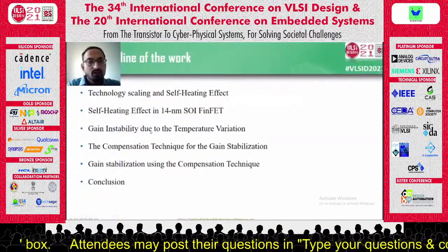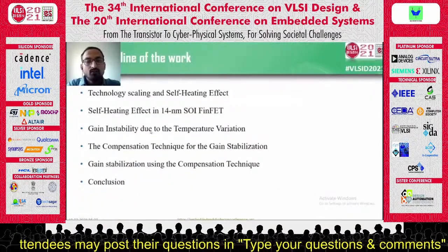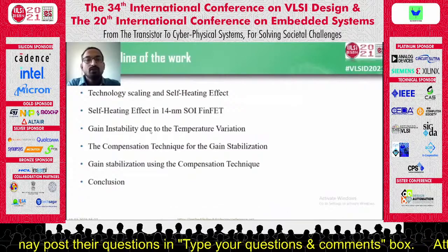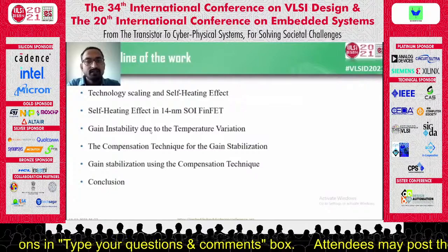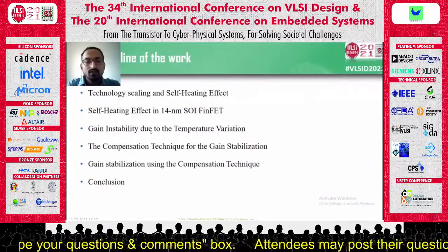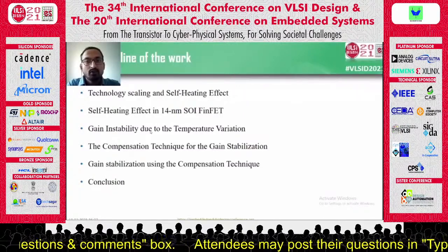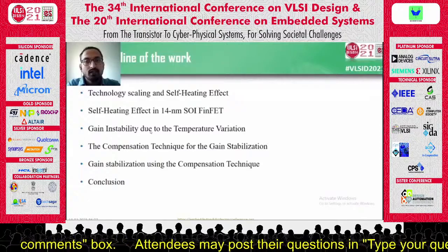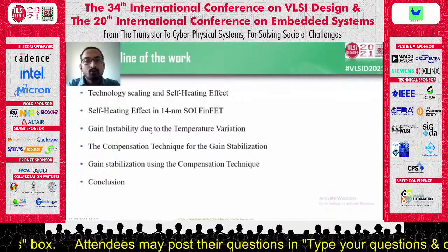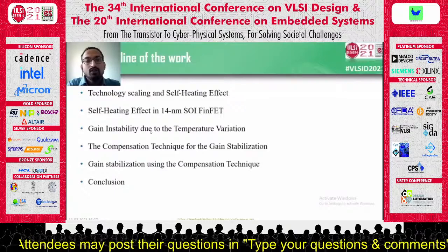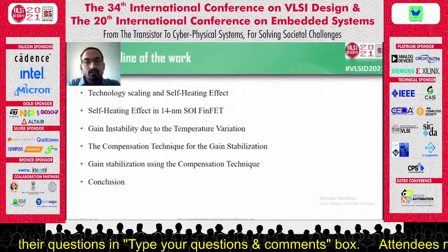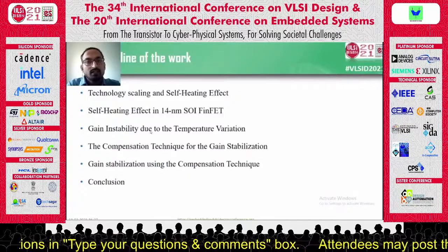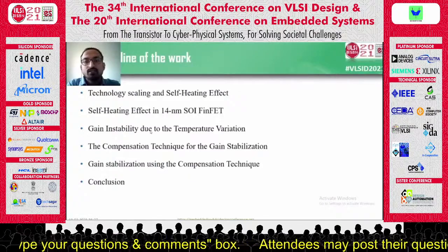Before giving you some facts and figures, I would like to give you an overview of our work. We are working on the analysis of various physical phenomena in FinFET devices and their implications on analog circuits. FinFET is an industry-adopted and very popular device due to its excellent performance in comparison to the planar MOSFET. However, due to the confined structure and buried oxide layer within the active region, the self-heating effect appears as a critical and important concern in these devices.